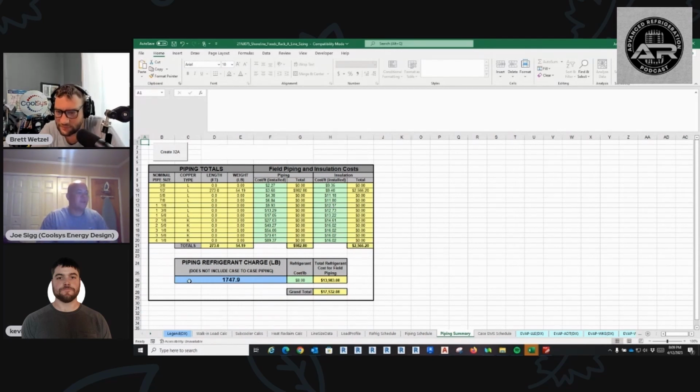No, there's 1,800 pounds in the system, and we size the flash tank off of that. We know that we want to be roughly 40% oversized with the flash tank, so that we have room for the gas volume to push down on the liquid. Basically, we don't want to size that flash tank for 100% full.